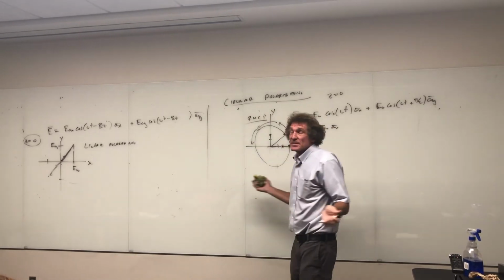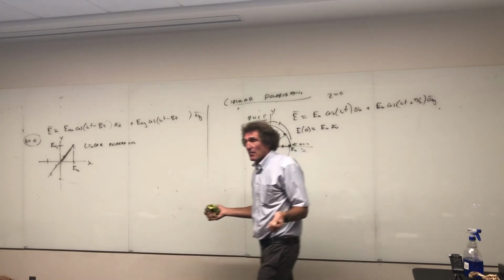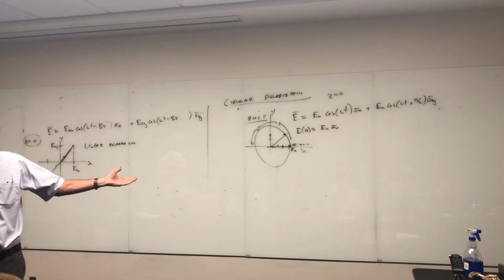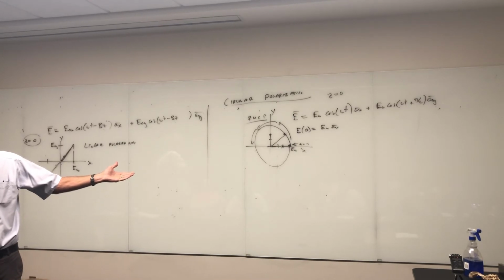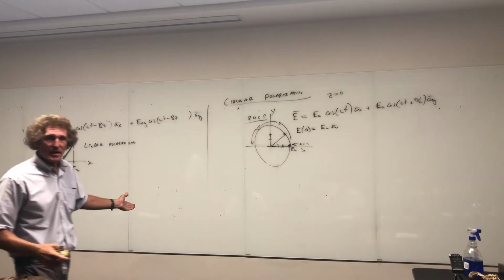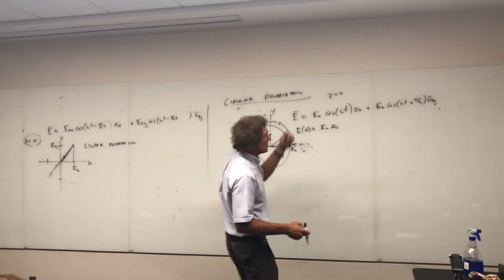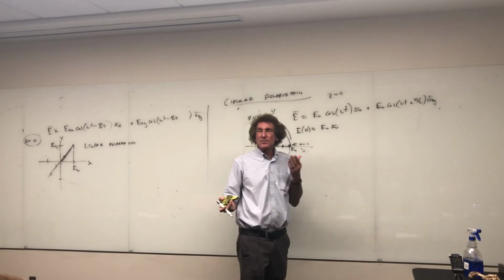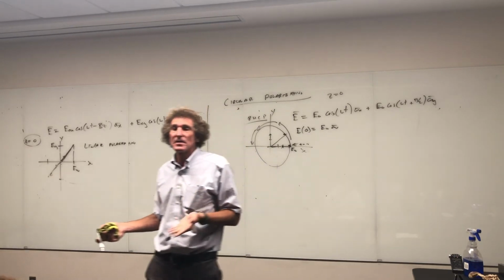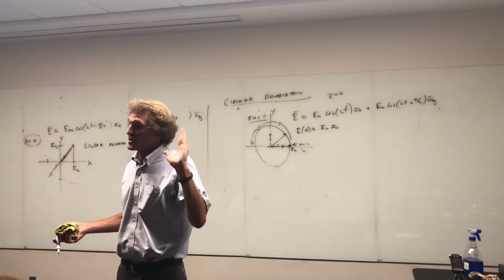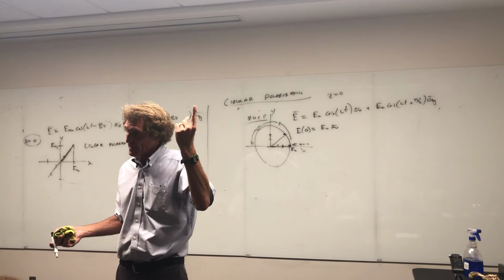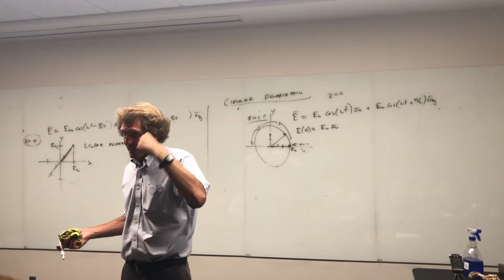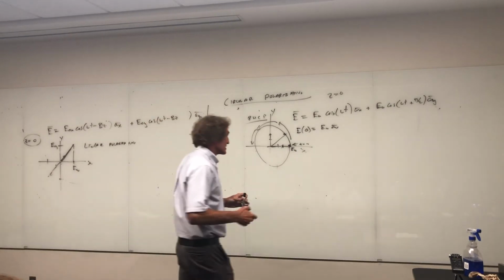So that's circular polarization. Now, remember, mathematically, there are a lot of ways to do this. I could write that in a phasor form, couldn't I, class? I can do this a lot of ways. That's why I don't get hung up on the math. Just plot a few points. It tells you what it is, left or right. Basically go at omega t equals 0 and omega t is 45, that's the direction it's going to keep on going forever that way. Follow? It's either going to be left hand or right hand. You all follow me on this, class? And that's why I don't get hung up with these things very much.